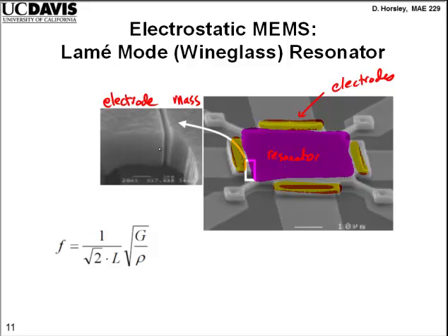And so how is this made? It turns out that this is a group from Cornell. They made this device using a technique called a focused ion beam, or a FIB. So they used a FIB to cut these slots. They went in with a focused ion beam and they just went zook right across, one cut for each electrode to separate this.